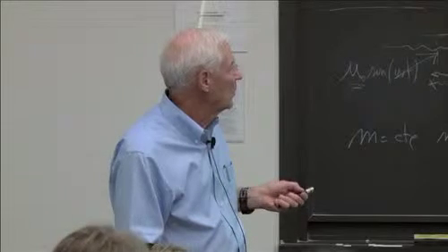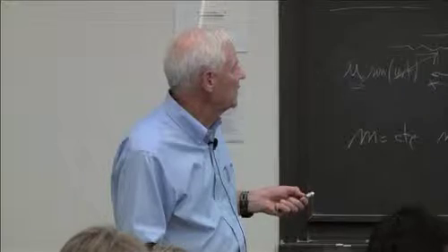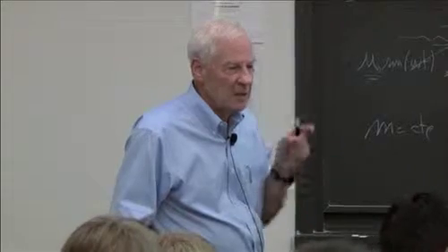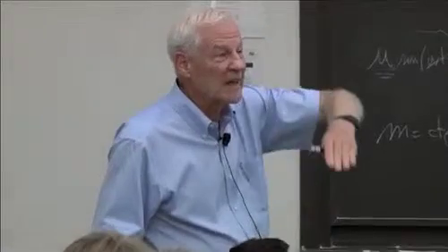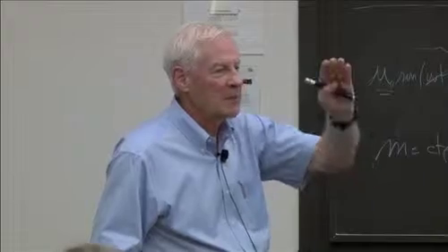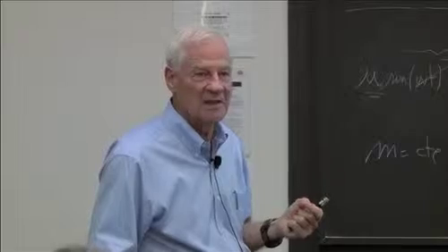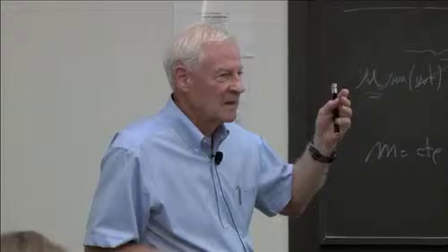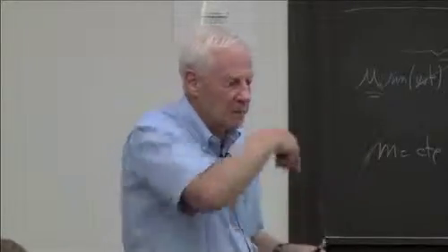Now, this reminds me of one more point. We typically measure the time and plot it at the initial temperature. What do the rapid compression machine people do? They plot their measured time at their peak temperature. Their temperatures decline due to heat transfer. If I don't remove the dP/dt problem, my temperatures climb. There's no reason why RCM and shock tube data should agree, because they both have opposite problems. Unless the times are short, then maybe the integral of the problem is not so big.